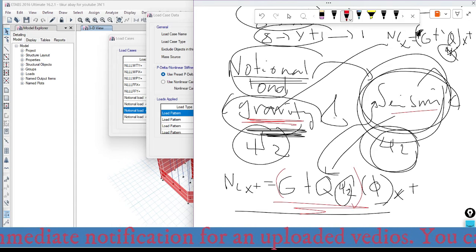But for gravity combination, we can use the load combination factor, that means gamma times the notional load in x direction.